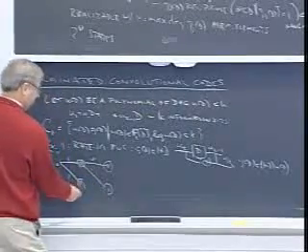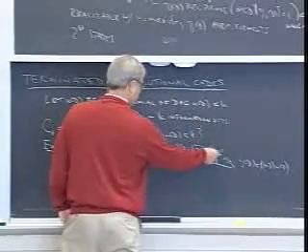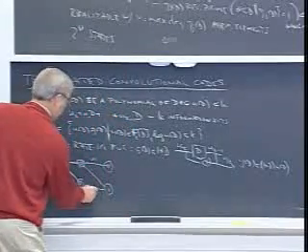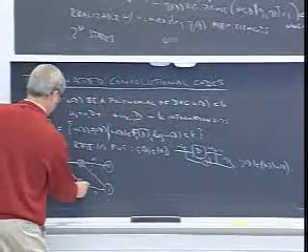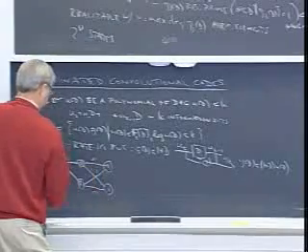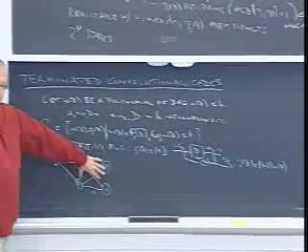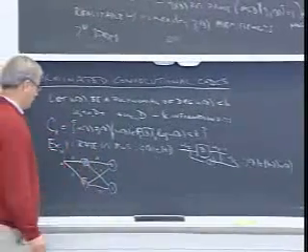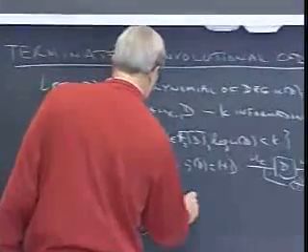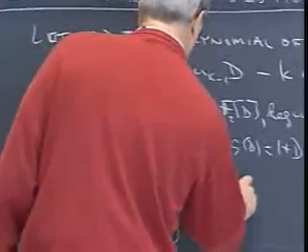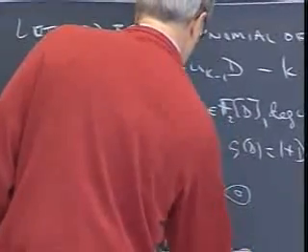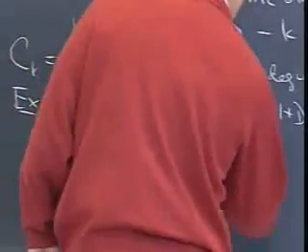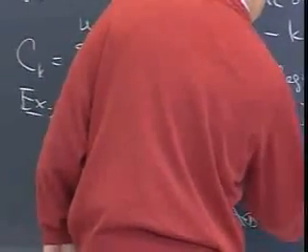If we get a 1 in, and we're in state 1, then the output is going to be 0 and we'll stay in state 1. If we get a 0 in, the output will be a 1 and we'll go back to state 0. So this is what a typical trellis section looks like here. We have all possible transitions between the two states. And so now it goes on for a while like this, time invariantly.